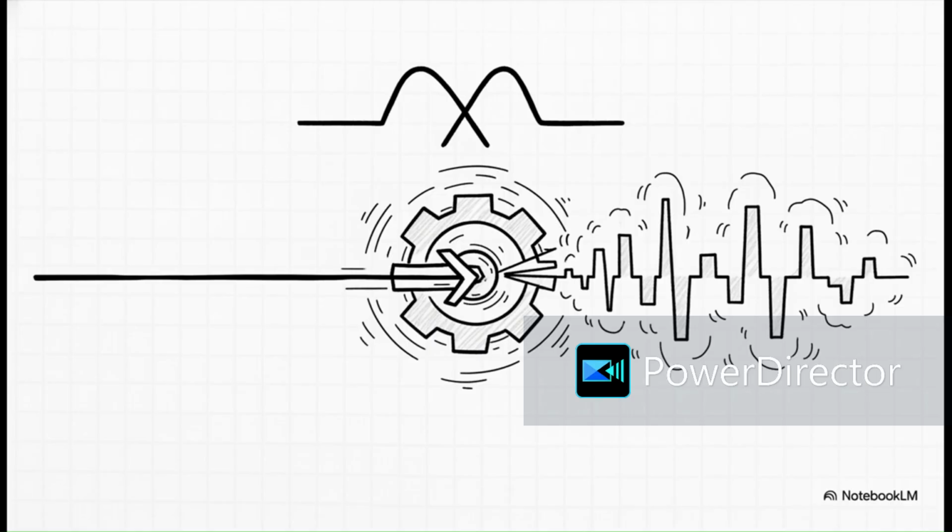It is exactly this rapid, continuous triggering that introduces disturbances and harmonics into the electrical system. You simply cannot rapidly chop a DC signal into thousands of tiny pieces to simulate an AC wave without creating some electrical noise. The sheer violence and speed of that switching permanently distorts the wave. So a pure sine wave? It's physically impossible to get at the output.